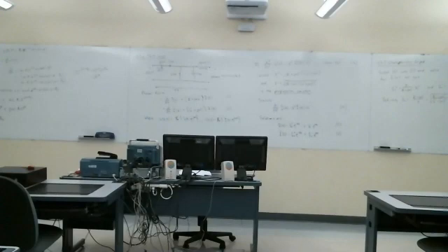The resistance, the inductance, again, these are all per unit length, the intrinsic conductance and the intrinsic capacitance of the line. And remember, these aren't really components in the line. This is a model for a transmission line at high frequencies.